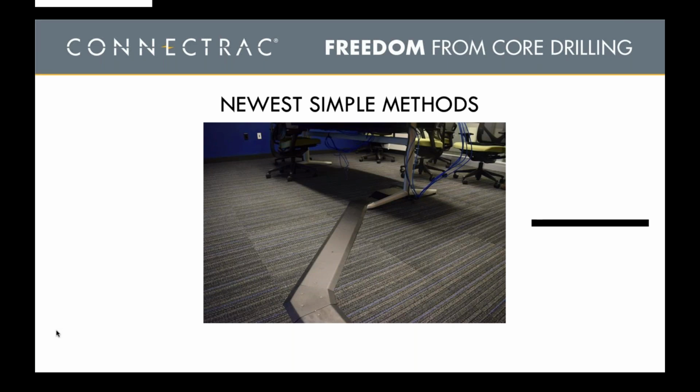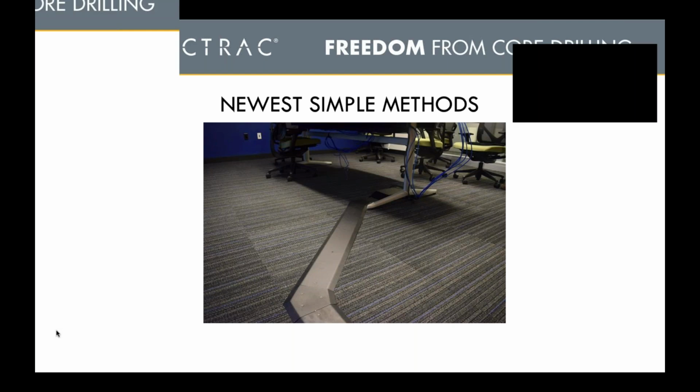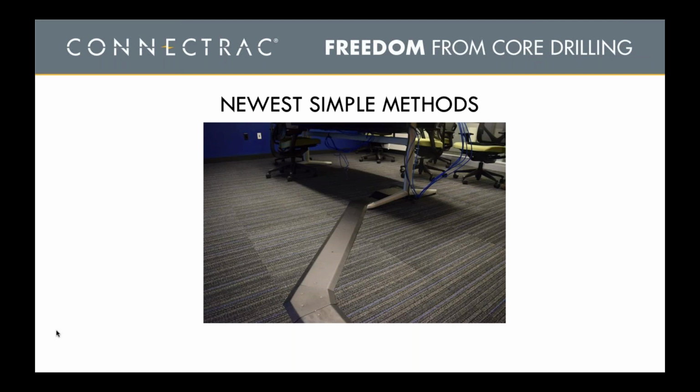It has a top and bottom steel shell that has raw wires inside this raceway. At the wall, which you can't see in this image, but under the workspace also, it has devices that the electrical contractor wires to provide you with the connectivity you need. It's often used because contractors are already familiar with other wall-mounted channels this company produces, and so they go to their supply house and purchase this for the horizontal floor distribution. It actually works good. It meets a need. But because of the lack of design, really, it's a pretty pragmatic, elemental system.